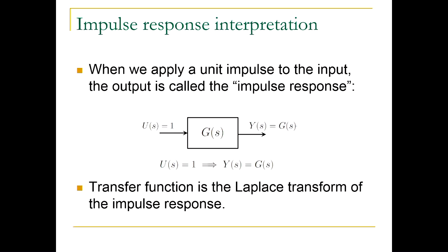It means that the transfer function can be interpreted as the Laplace transform of the impulse response of the system. Can everyone see that? The transfer function is really the Laplace transform of the impulse response. You apply an impulse to the input, you observe the output, take its Laplace transform, and that's the transfer function of your system.